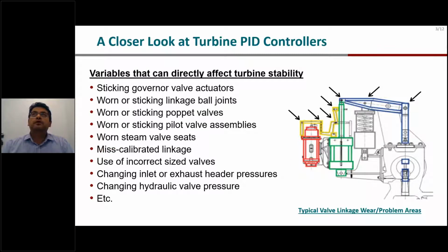The valve seat itself gets older and older and allows more steam to come in. This is something that might also happen during the engineering stage, where you incorrectly selected or sized the actuators or the valves. So you have some inherent problems that you need to accommodate while you are tuning your system, since the valve itself is incorrectly sized.